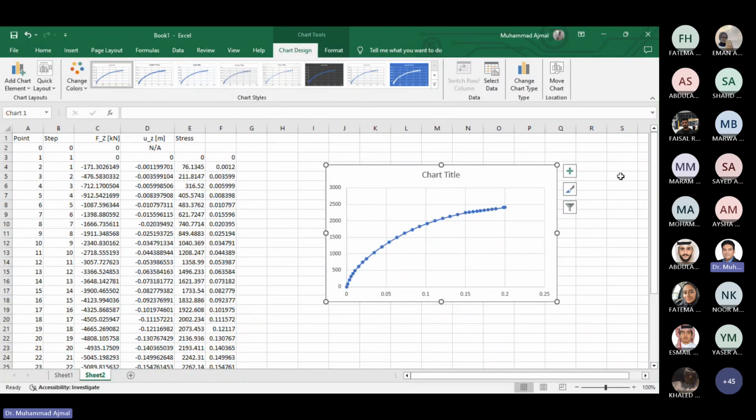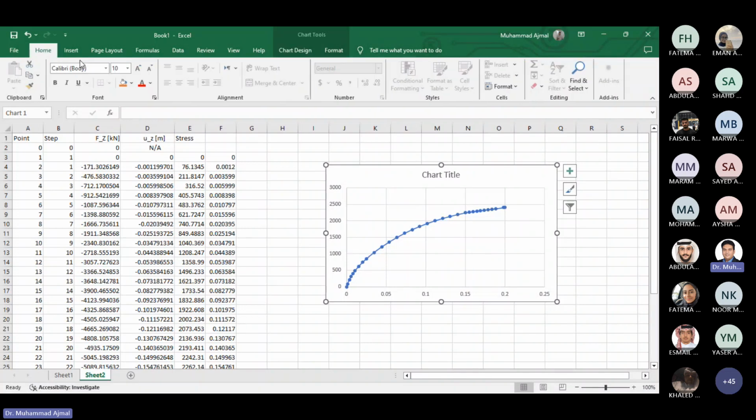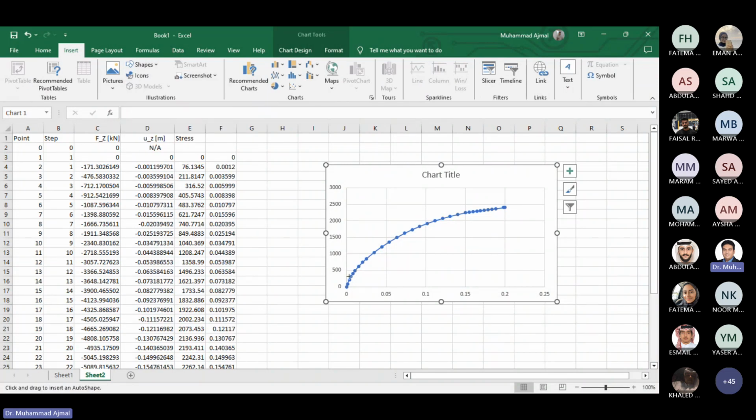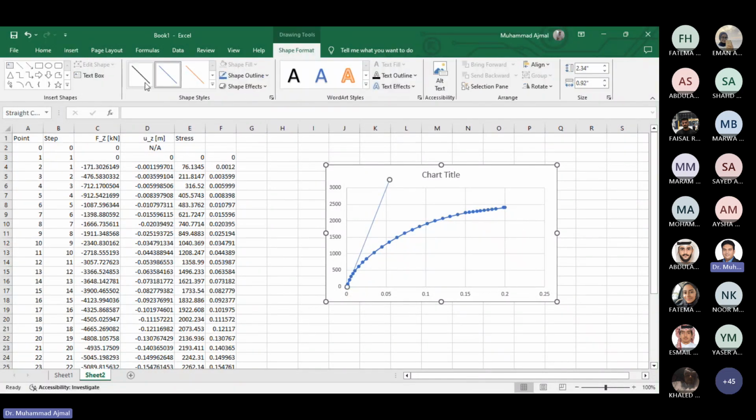In our second chapter, when we learned about exploration and carried out the plate load testing, I told you that through that load displacement curve you can find the bearing capacity. So we are going to use the same concept here. I will use a tangent. If you don't have a smooth curve or a pure flattening curve, you can draw a tangent by considering your points on your graph, and wherever they intersect, you can go to the y-axis.